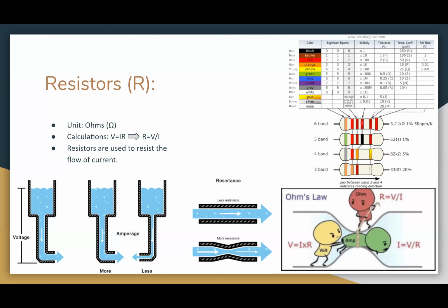The next colored band is your multiplier. The arrow goes up to where it says multiply by 10. So 321 times 10 is 3,210, aka 3.21 kilo ohms. And if you look to the right side, it says 3.21 kilo ohms.